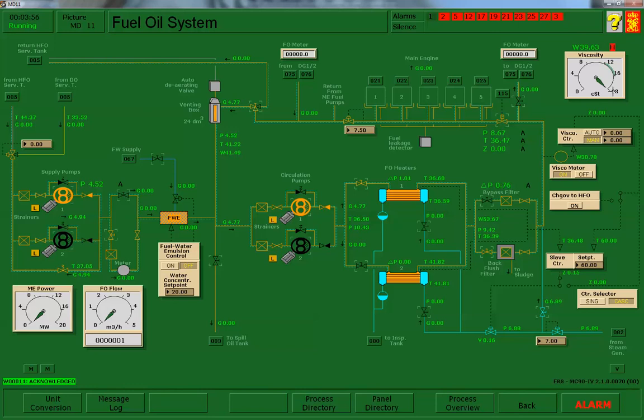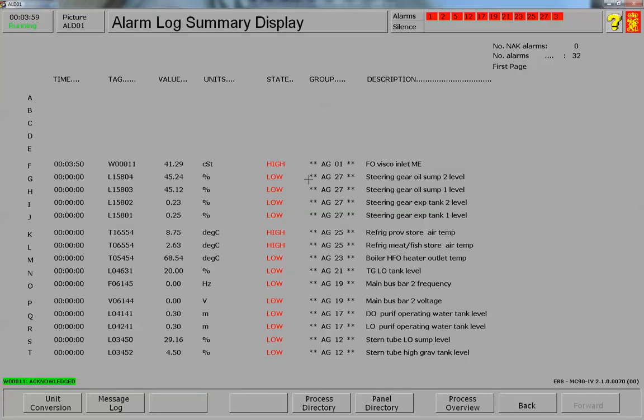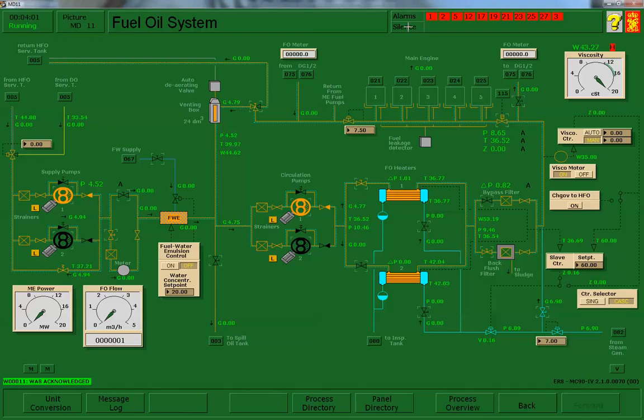Now, what's going on is normally it will come up with a viscosity that's quite low. I'm glad this happened. This is the other type that can happen: I came up with very, very heavy fuel, 47 centistokes, and we have to be down in this 12-16 centistoke range to operate. So this is the unusual case that happens occasionally. Now, I don't plug this in. This is actually just the way the simulator starts up. Let's go ahead and halt this.